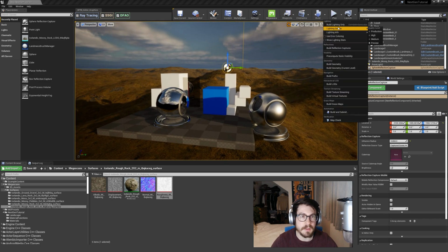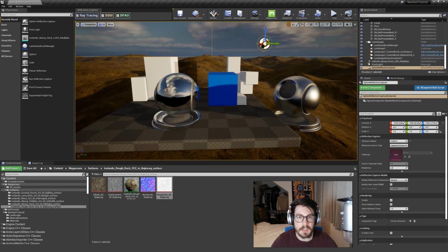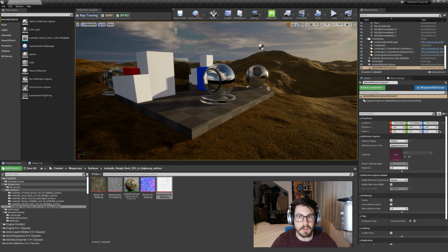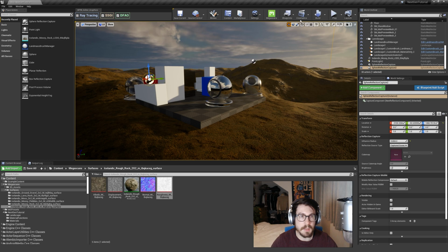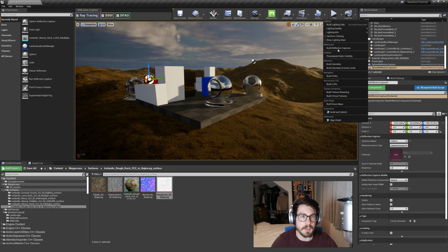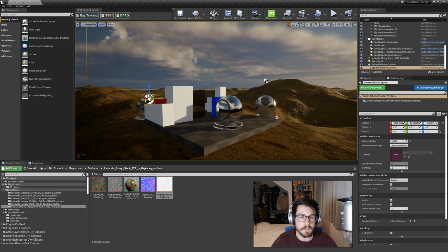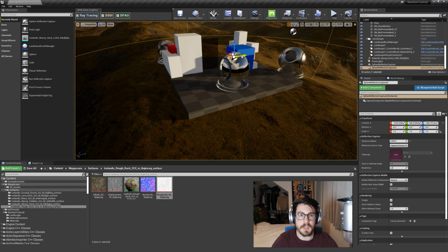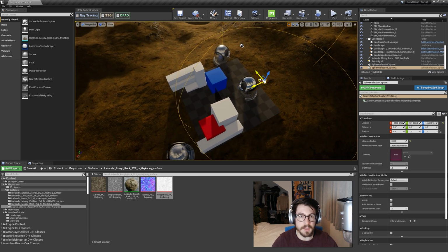And also we can build the reflection captures. You can just go here on this little arrow, build reflection captures, and then it updates again as well. If you have multiple and you then start building the reflection captures, it blends between multiple angles correctly. So usually what you want is one large one and one that is a bit smaller for the smaller details around each object.